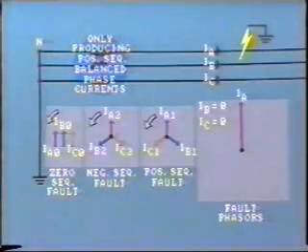So we now come to another very important conclusion, and that is, where a ground fault exists, all 3 sets of symmetrical components are present. That is, positive sequence components, negative sequence components, and zero sequence components. And do note that within each set of components, the voltages and currents are of equal magnitude. The presence of these components provides a useful tool for detecting unbalanced conditions and ground faults.